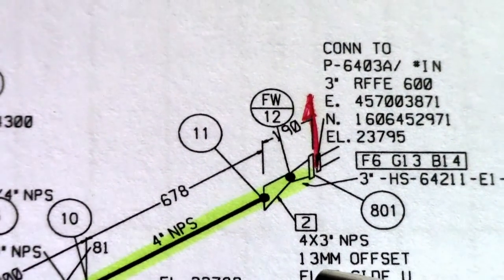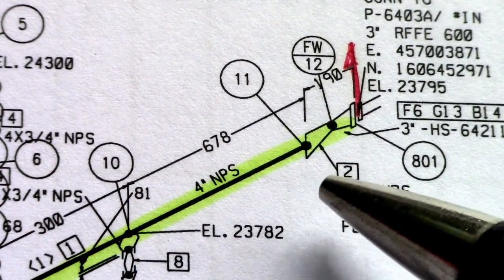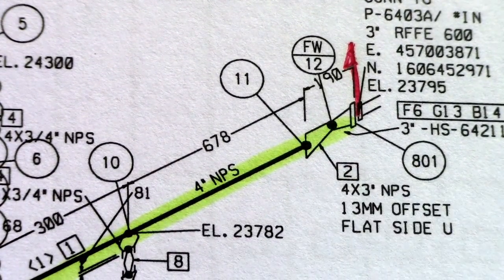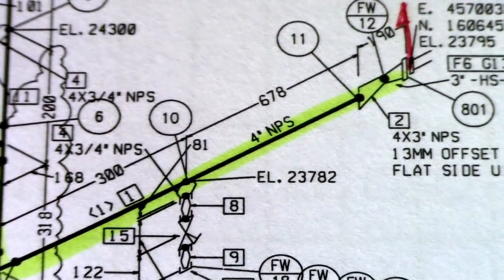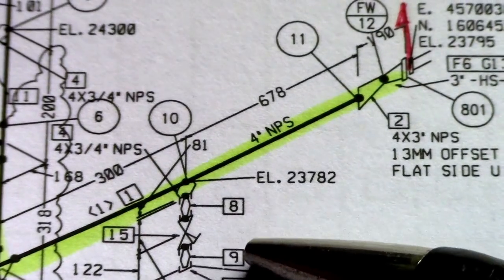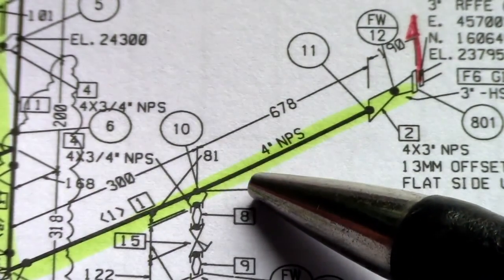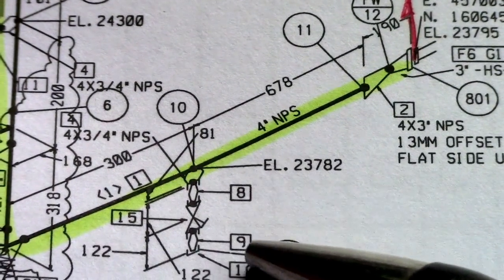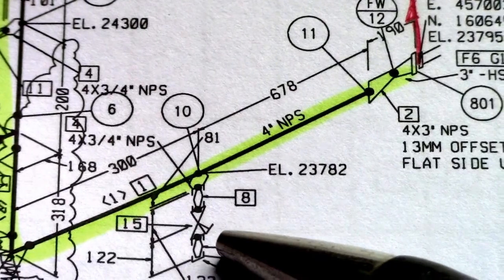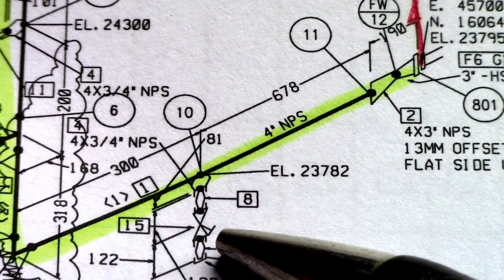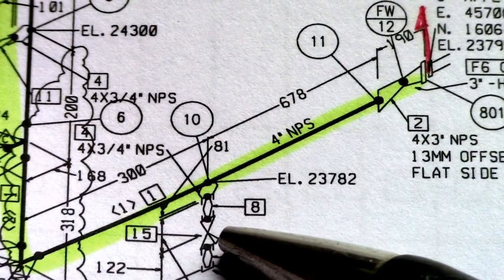Sometimes they also have tack welding on the valve, but just comment on that one. So these are fittings connecting to the pipe. Check all the joints if already welded. Also the orientation of this valve. Check the code and orientation, what type of valve this is.